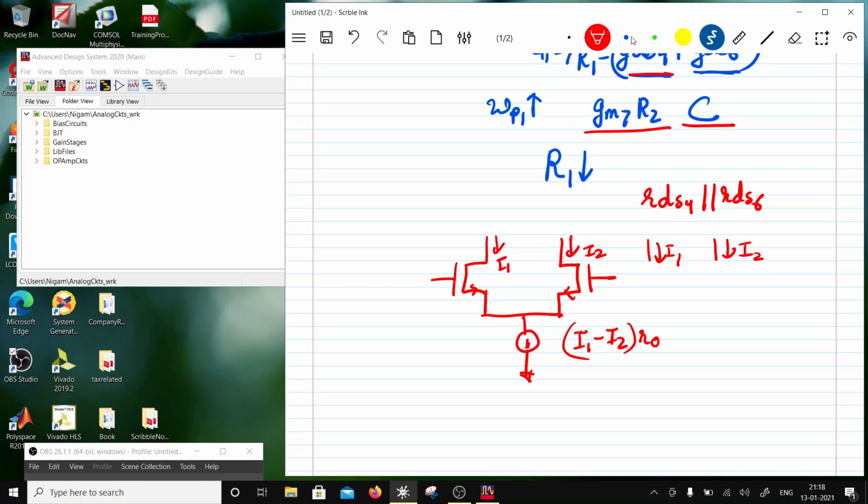So I transfer the impedance to the output node in this branch, and my output impedance is going to be high. That way I can make the gain high. Now I was doing this with a common source: I was going differential in and single ended out.